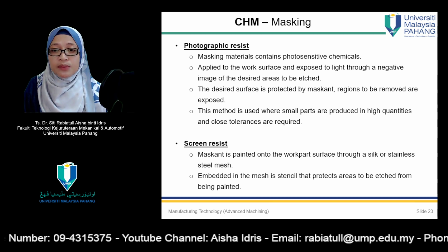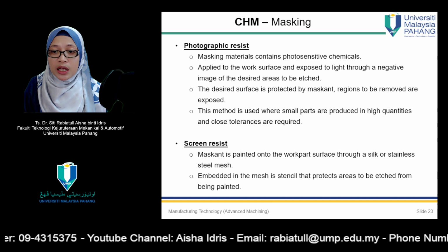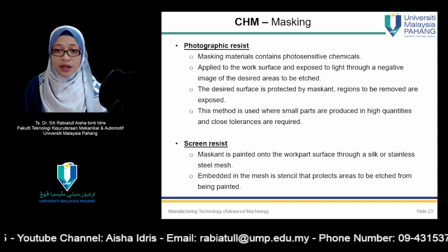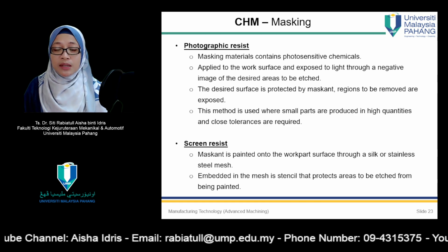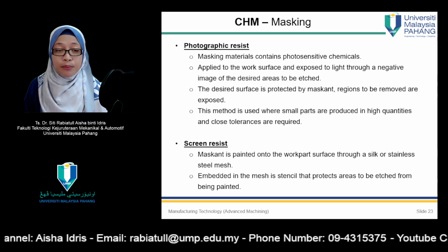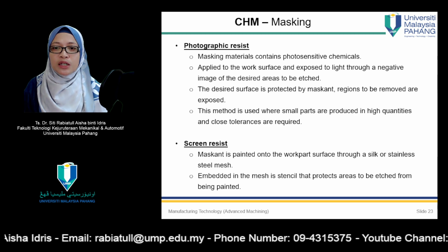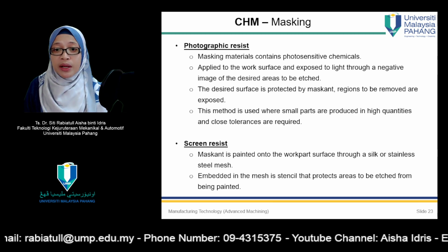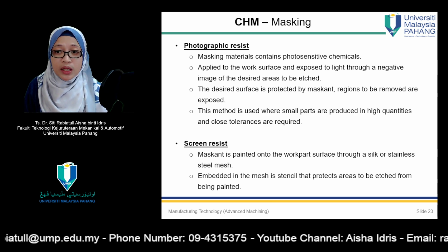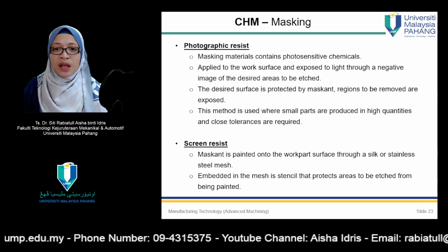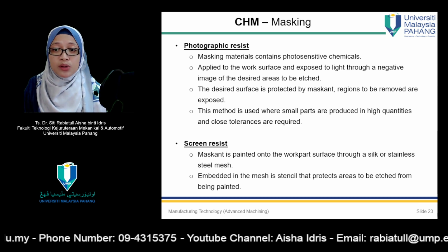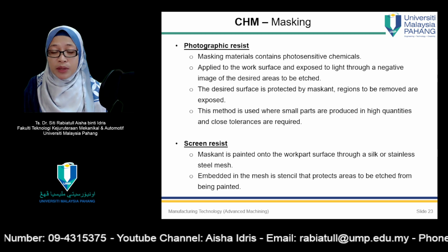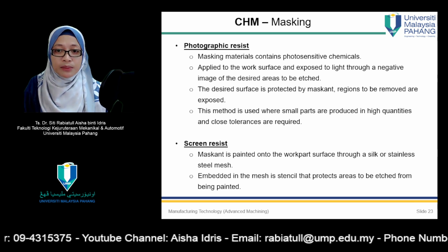The screen resist method is generally used in applications that are between the other two masking methods in terms of accuracy, part size, and production quantities. Selection of etchant depends on work material to be etched, desired depth and rate of material removal, as well as surface finish requirements. The etchant must also be matched with the types of masking that is used to ensure that the masking material is not chemically attacked by the etchant.